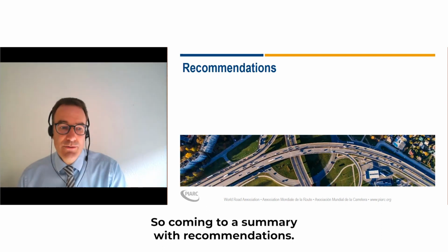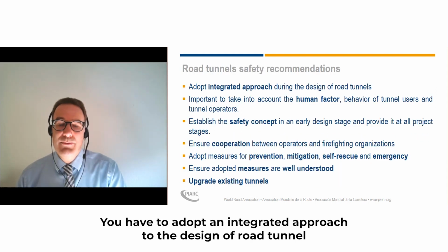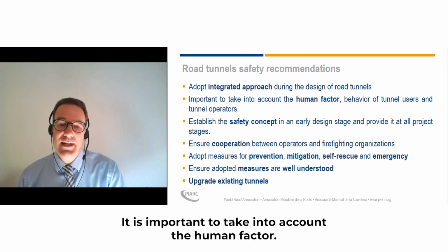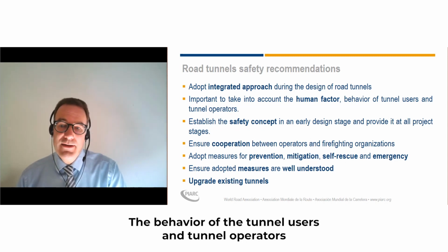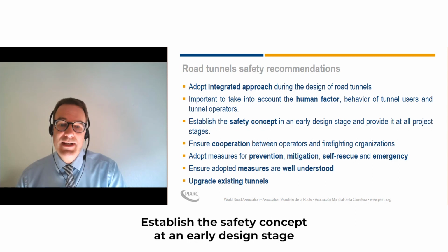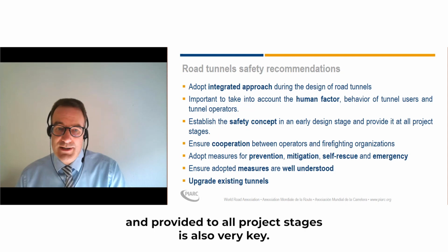So coming to a summary, with the recommendations we could have here, you have to adopt an integrated approach to the design of a road tunnel. I mentioned this at the beginning of my presentation. It is important to take into account the human factor. The behavior of the tunnel users and tunnel operators is a very important part of tunnel safety. Establish the safety concept at an early design stage and provide it to all project stages. This is also very key.